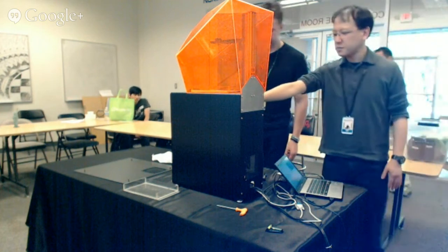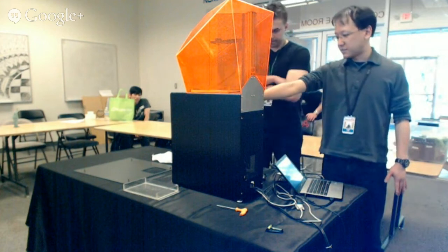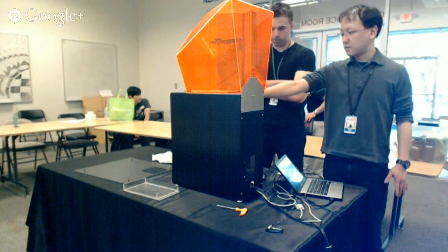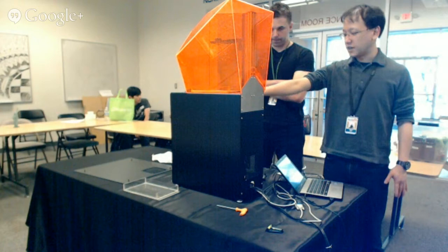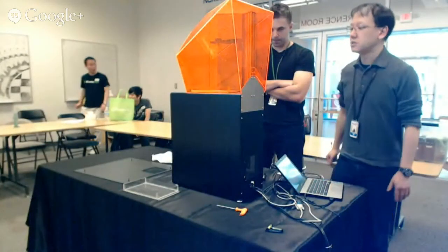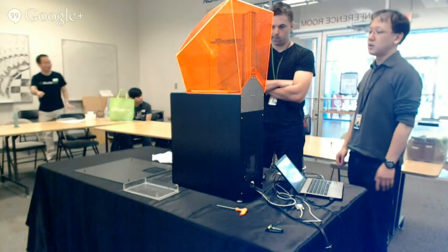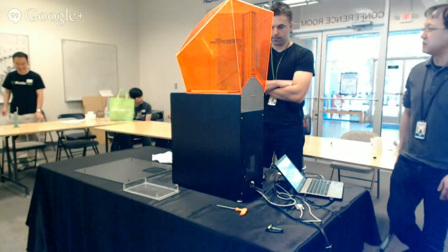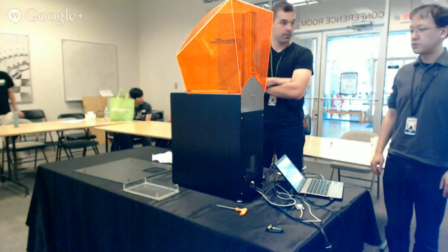First, you need to recalibrate the levelness. It's got to be level, so all the tilt, you've got to make sure that you get that right. And then the dimensional calibrations, the slicer, how big is the pixel? You have to do that again.